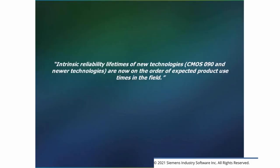Intrinsic reliability lifetime of new technologies, CMOS 90 and newer technologies, are now on the order of expected product use times in the field. This is a quote from a major IC manufacturer for the automotive industry on aging. So far, we have been analyzing the causes and the symptoms of aging due to HCI and NBTI mainly. From now, we shall be looking at possible remedies.